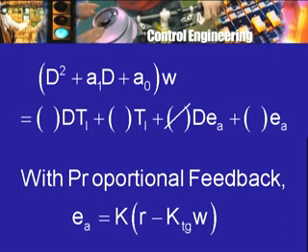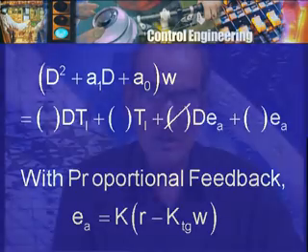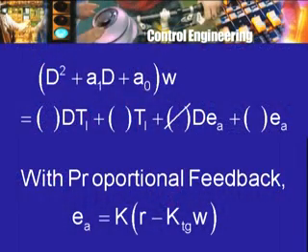Now, what is happening is that because of this proportional feedback, we are changing this coefficient A0 of the characteristic polynomial. By changing A0, of course, the roots will change, and therefore, one can find out the effect of this change. This is the kind of thing for which the root locus method is appropriate, and in this case the polynomial is only a quadratic. So, one can write down an explicit formula for the roots of this polynomial and see the effect of this gain coefficient k on the nature of the roots.